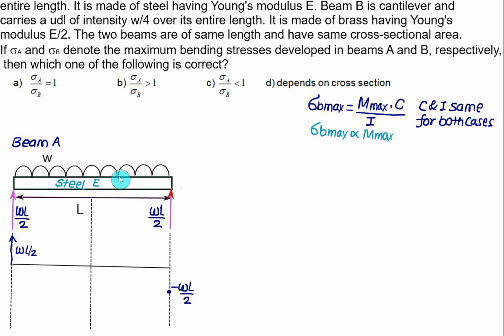If it is a rectangle in the load, then we get a triangle in the shear force diagram. By symmetry, exactly at the center, equal to L by 2, the shear force changes sign, that is, the shear force equals 0. On the left-hand side the shear force is positive, on the right-hand side it is negative, so there is a sign change. At this point C, we have the maximum value of bending moment, which can be obtained from the area of this triangle.